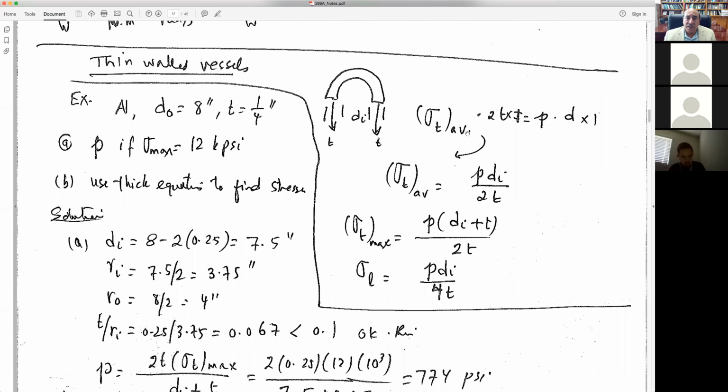Now the stresses, we reviewed some of the main stress systems, and we wanted to be familiar with the equations, how to apply the equations, and in what type of application. First, we started with thin tubes. And the thin tube is a very simple system. When you have a pressure inside, you do a force balance, you get a tangential stress that is equal to pressure times the diameter Di over 2t.